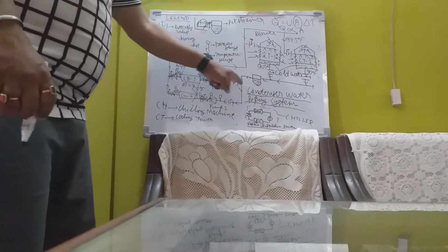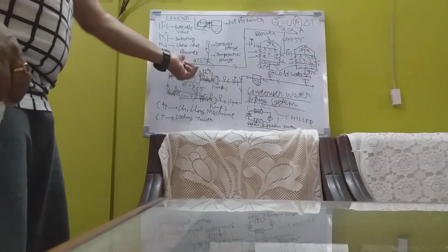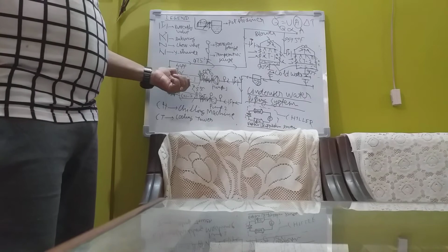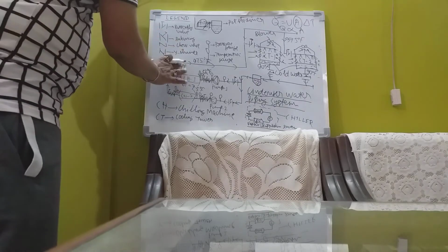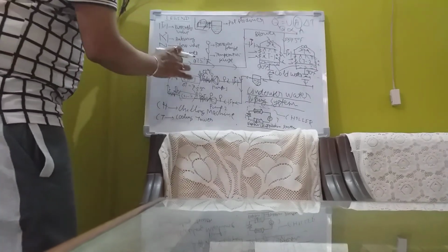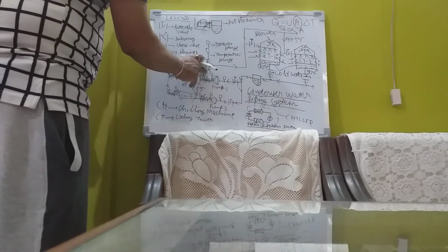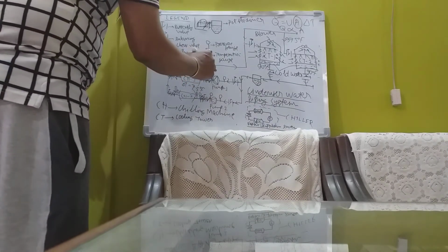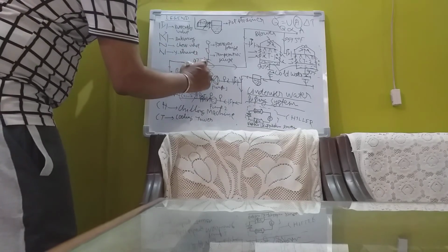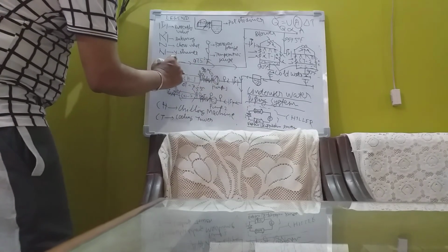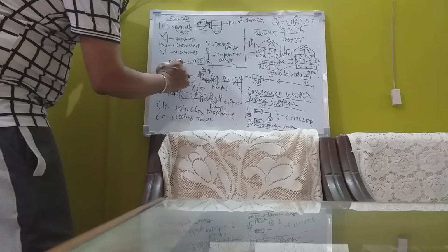This water at 90 degree Fahrenheit comes to the condenser, picks up heat from the condenser of the chilling machine and gets heated to 97.5 degree Fahrenheit. That means it comes at a temperature of 90 degree Fahrenheit and it gets heated to a temperature of 97.5 degree Fahrenheit.